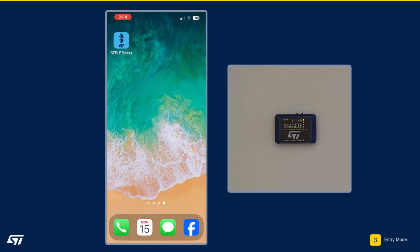Once you have powered on your board, you should see all of the LEDs cycle rapidly, then turn off, and after a couple of seconds, the green LED will turn on and stay illuminated. It's now ready for you to connect via the mobile app. Launch the STBLE Sensor app.